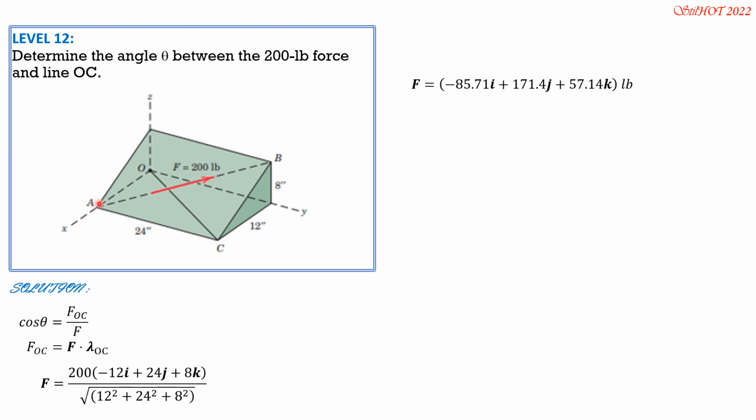12i from O along x, then along y, 24j, divided by the distance, square root of 12² + 24². So (12i + 24j) over the square root of 12² + 24². In decimal, the unit vector OC is 0.4472i + 0.8944j. Then obtain the dot product.